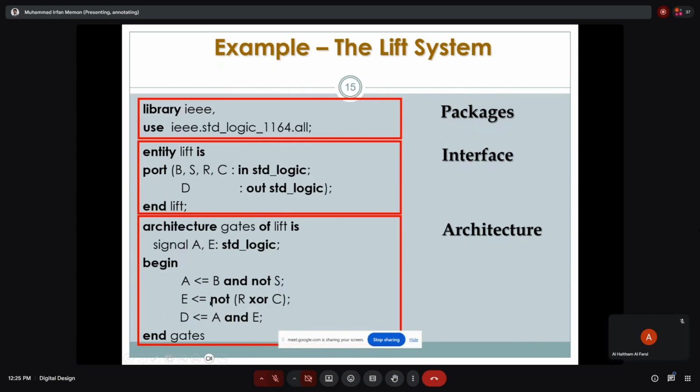Okay, so exclusive OR is a complex gate which is a combination of AND, OR and NOT gates. That is A bar B, where A bar means not of A, and plus is OR. So these are the Boolean expressions for exclusive OR, and then A B bar, so A ANDed with not of B. All of this together results in the exclusive OR.